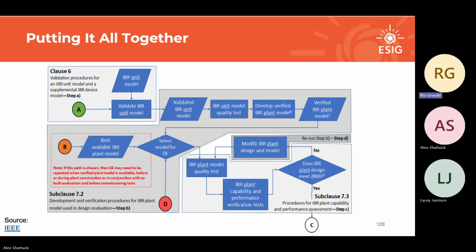if you're doing this in the EMT, you're doing this more than once. You're doing all of the tests more than once because you can very easily fix performance for one and make worse performance or lose meeting conformity with the other. So it's this recursive type of testing. It's very similar to the process we talked about in the example yesterday of fixing two contingencies, running the other contingencies to make sure nothing bad happens. So that's the design evaluation process and a flow chart with model validation pieces.